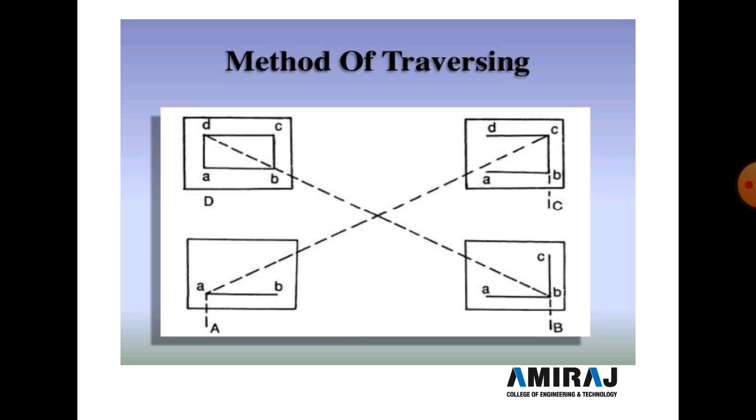all the setup is transferred to the B point, and from B bisect the A point ranging rod. On B a wooden peg is marked, and the A point and C point are marked by ranging rods. From B the three steps are repeated: leveling, centering and bisecting or orientation.